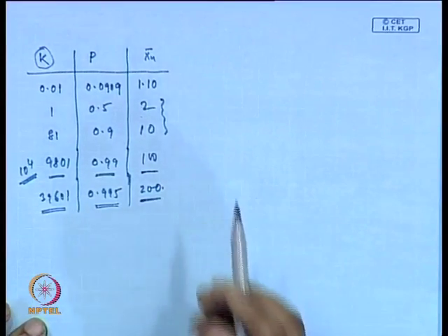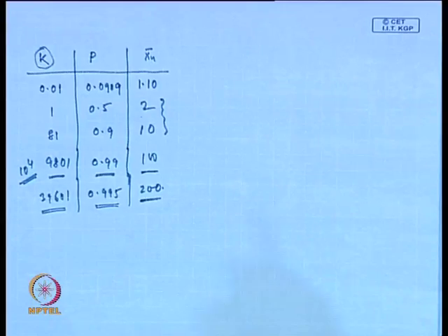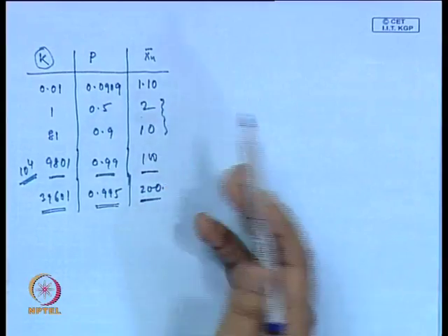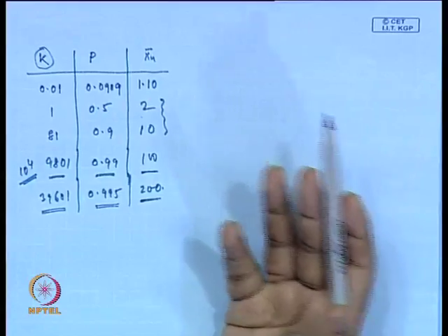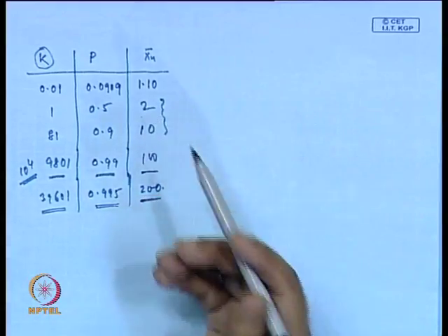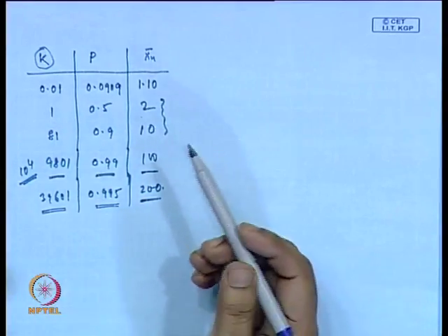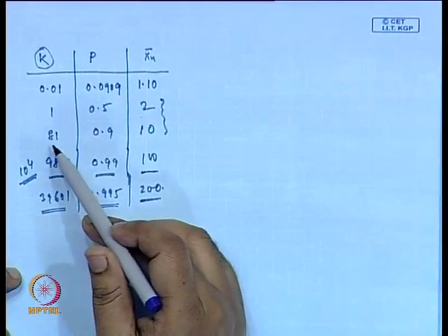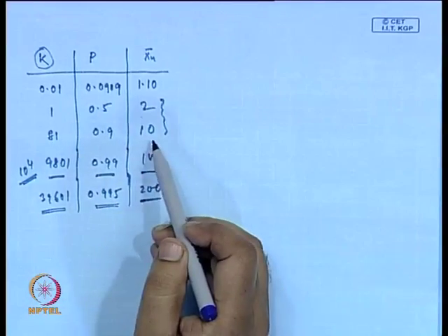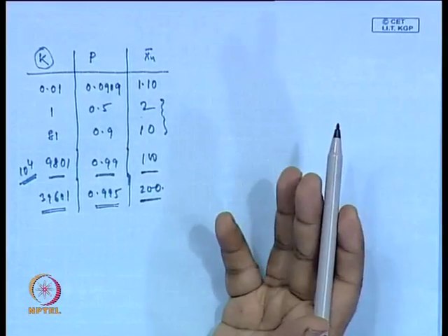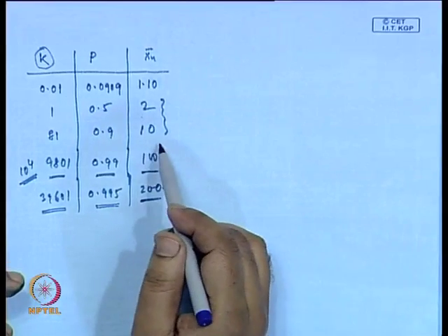Okay. And if you do not remove your condensate or the polymer, if you wish, then your reaction will end up at an oligomer stage, maybe dimer, trimer or tetramer, a mixture of that, but the average will be say a dimer for an equilibrium constant of 1, and for an equilibrium constant of the order of 10 to the power 2, it will be at the stage of xn about 10.